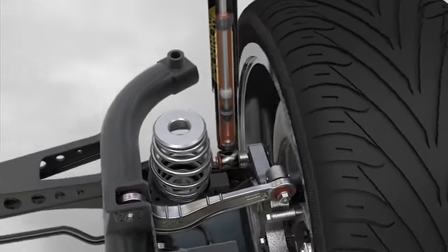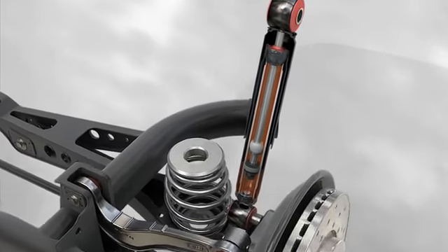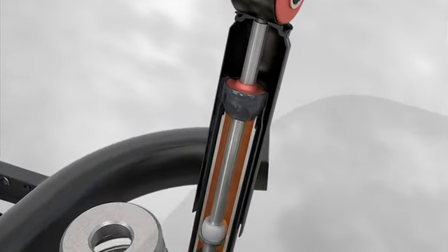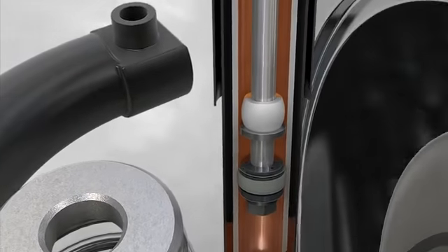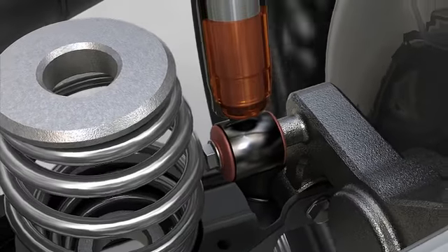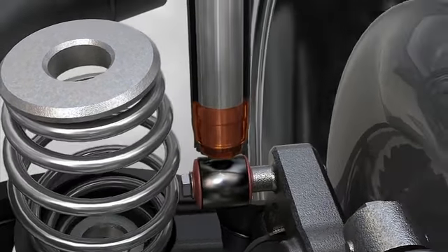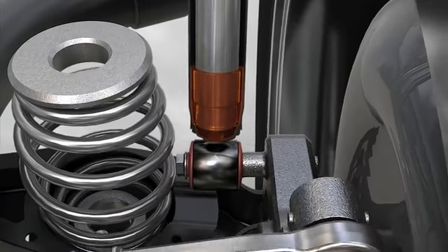For the shock absorber to perform its function properly, the working chamber must be full of oil at all times. Otherwise, the valves will be operating in air, causing them to malfunction. The reserve chamber will always be partially full of oil because its function is to ensure that the working chamber fills with oil, regardless of how compressed the shock absorber is.